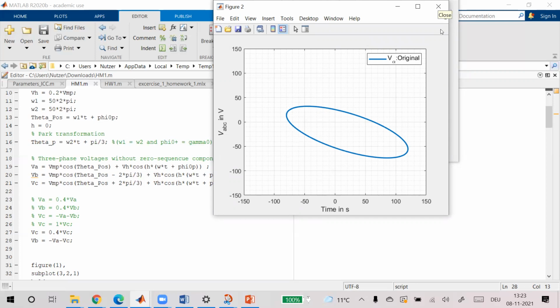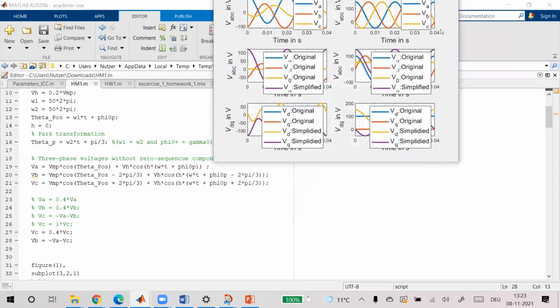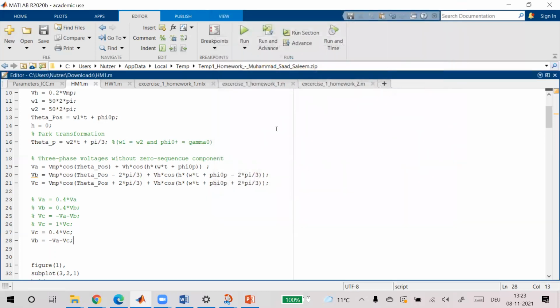So the sub operation, harmonics, faults. Yeah, looks like everything is covered, but now we just have to do the same thing in Simulink. Okay, so now we have to move to the Simulink part, but this is all about basically the transformation theory. So you can see that we did a lot of test cases to show you different things in the alpha beta frame and DQ frame. This is just to make you familiar with the DQ transformation.